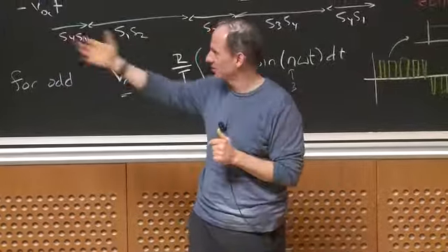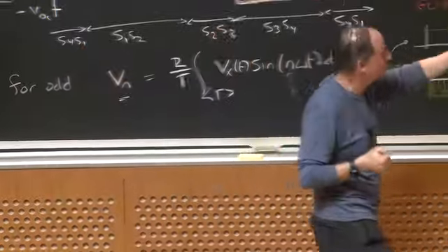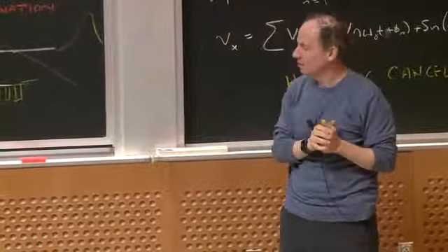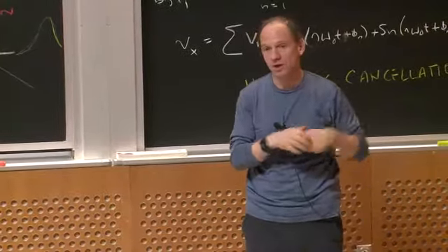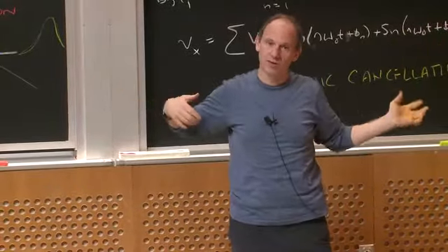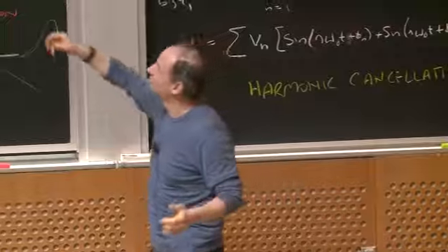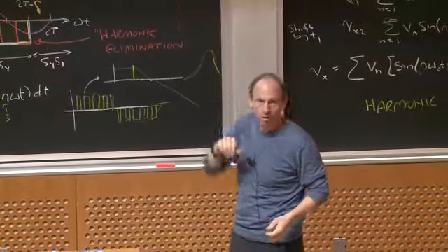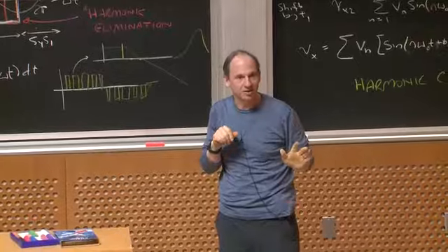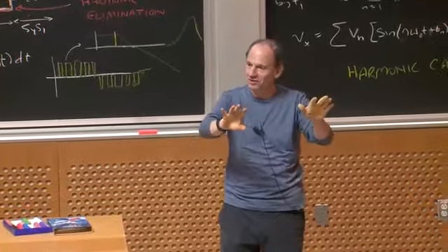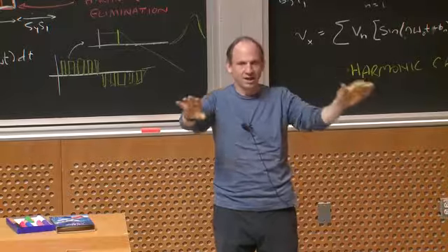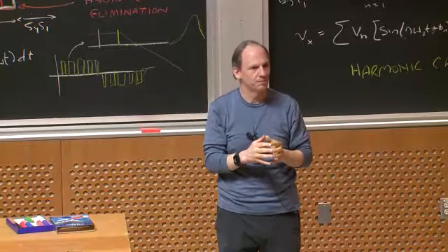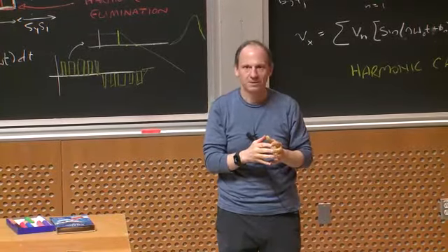It's widely used. It's used in DC-DC converters. It's also used to kill off unwanted harmonics in inverters. Harmonic elimination is also used, and there's nothing that says you couldn't do the two together. You sort of saw that, right? Instead of using just one pulse per half cycle, I could use some pulses per half cycle to eliminate some harmonics, use some phase shift and eliminate some more, and I can intermix those two, and they give very nicely, easily filtered waveforms. Any questions about that?